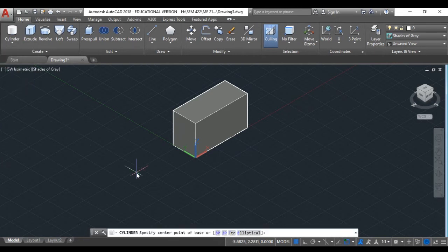So if I click on the cylinder shape, I can locate the center. If you click anywhere in that screen, guys, the program will consider it as Z equal to 0. Don't think that if you are clicking somewhere away from the box, I'm not speaking about the box, guys, okay? If I'm picking any points here or there, by default the program will consider X has a value, Y has a value, but Z is 0, right?